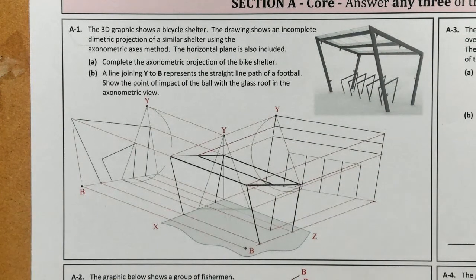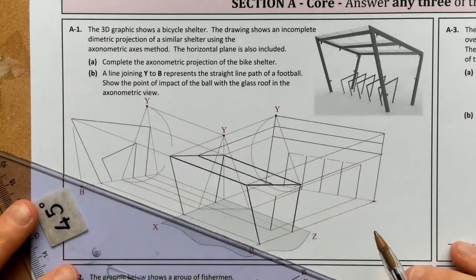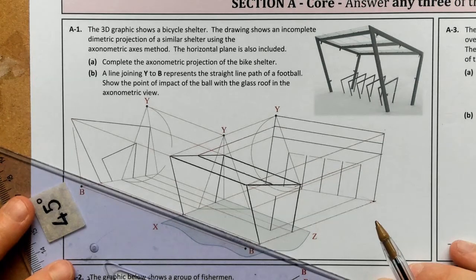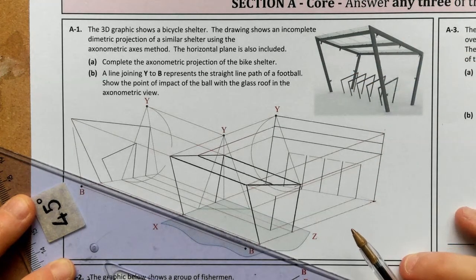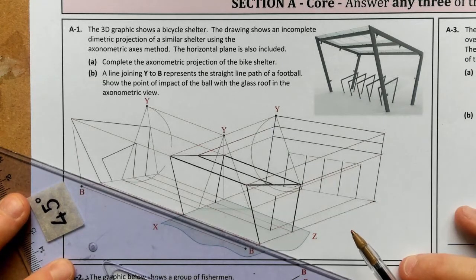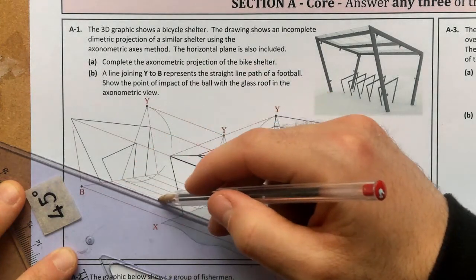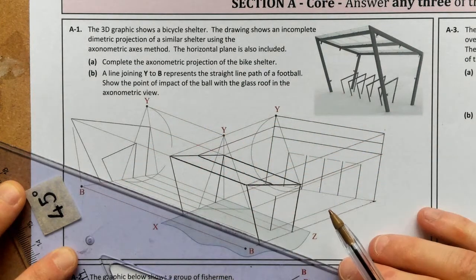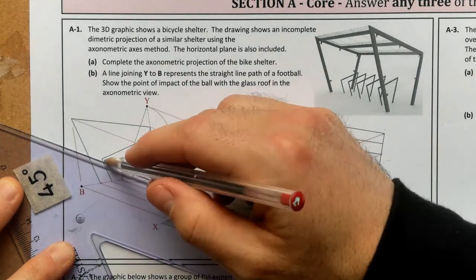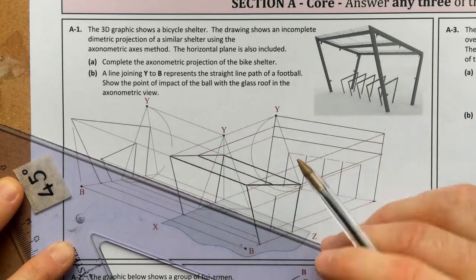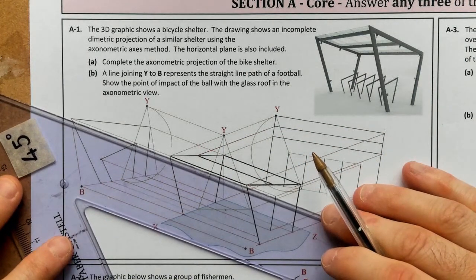Okay, so to find the middle section, I'm going to project down all of these points at once, just to have them done once again. So I'm getting the inside parts in here. Make sure as accurate as possible. Neatness is important. I'll come down a little bit further just to have it long enough. And I think these ones are already projected down, so that one's okay.